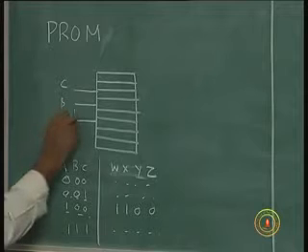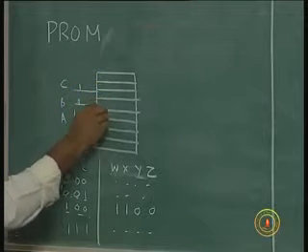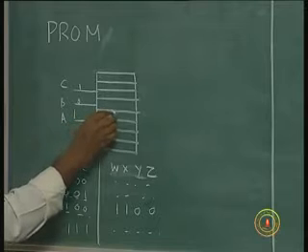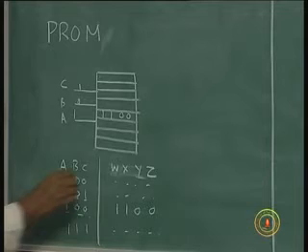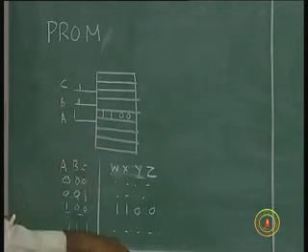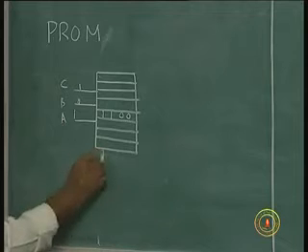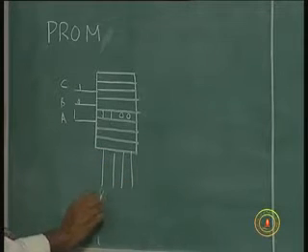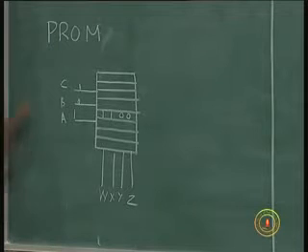As soon as you make 1, 0, 0, let us say this is 0, 1, 2, 3, 4, value 1, 1, 0, 0 would be written here, which I will be able to read off. This is a read-only memory. There is no programming here. I just give the value. I get the truth table. I etch it in hardware, as you will.